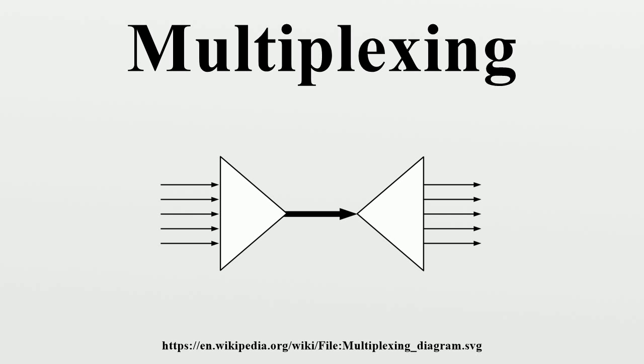Space division multiplexing in wired communication. Space division multiplexing is the use of separate point-to-point electrical conductors for each transmitted channel. Examples include an analog stereo audio cable, with one pair of wires for the left channel and another for the right channel, and a multi-pair telephone cable, a switched star network such as a telephone access network, a switched Ethernet network, and a mesh network.